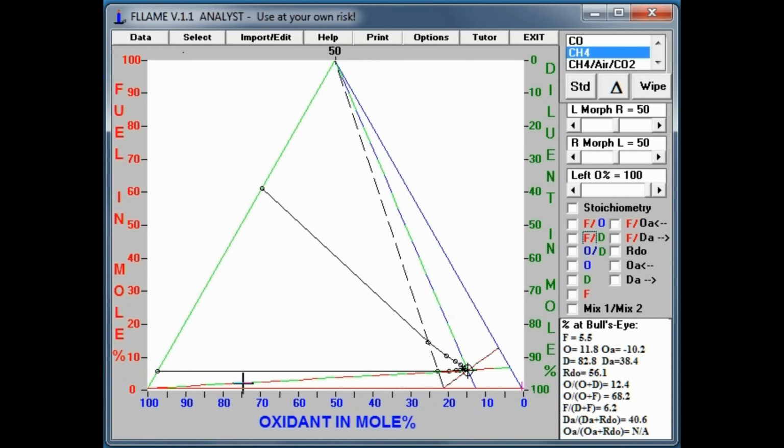However, we could also add nitrogen to this point where the vessel contains about 11.8% methane with nitrogen, then purge air to get to the air point more quickly and with less purge gas expense. Then purge to oxygen if desired.